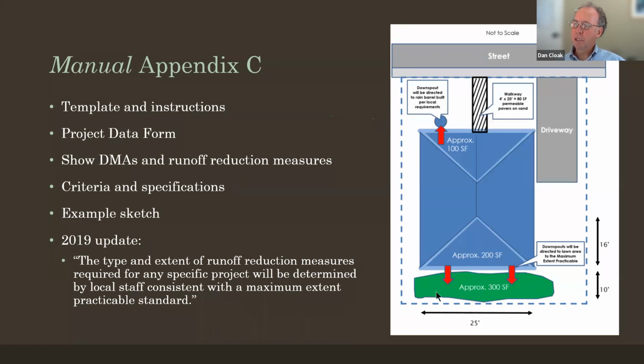I think if you looked at this example here with the discharge of 200 square feet of roof area runoff discharging to 300 square feet, now, this is 3 times the minimum 2-to-1 ratio here. And so how much of a stricture would you want to put on this area in terms of requiring that it be graded so that it tends to pond water that runs off onto it rather than letting it flow off?